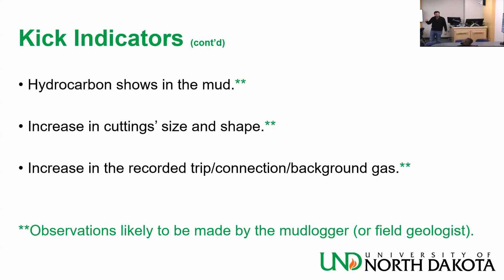So I'm drilling now at 10,000 feet, but the mud and cuttings coming out from the well are from 7,000 feet. I need to stop drilling and keep circulating, then I get a higher lag depth, and then I get to the same depth as the bit. But generally, as you are drilling, you're about 1 hour behind. That means if I'm drilling now at 10,000 feet, my lag depth is the depth I was at 1 hour before, something like that. And there are correlations on how to get that.